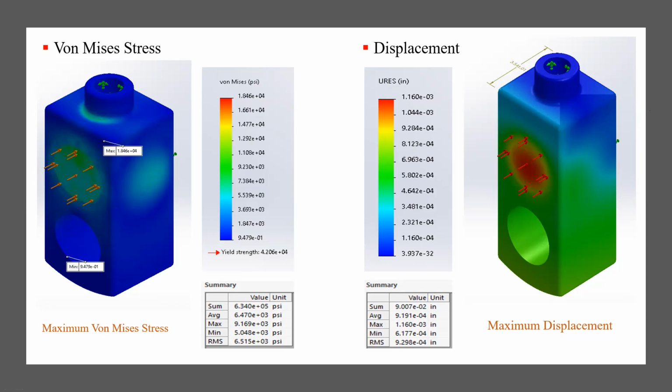On the SolidWorks FEA, we decided the fixture area on the place where the stem is threaded with the gate, and around where the seat is located. So the green color here shows the place where the seat is located and touches 100%, touches completely with the surface of the gate.